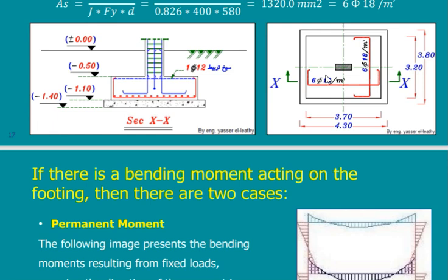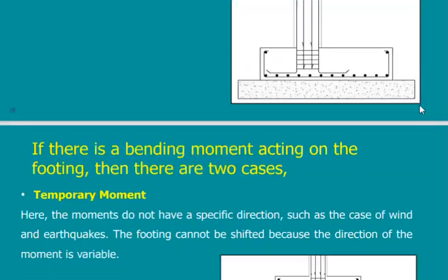If you tell me the full number, then I don't have to calculate it, because if you give me per meter and I multiply by the width, I would have 20.5 rebars, so I will use 20 or 21. It is better that I give the total for the contractor. But both are okay and both are the same, and whoever checks it is an engineer, he can give a decision, and it's okay.